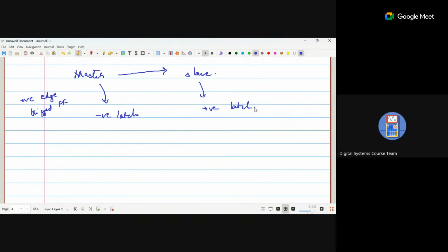Okay. So now the circuit for this side. So this is a negative latch. How is your negative latch? You have a multiplexer, 0, 1, and then you have a clock bar. You have input D. Then you have Q. We call this QM, which is intermediate, in between. So this is the Q from the master. Okay. And this Q will be again given here as well.